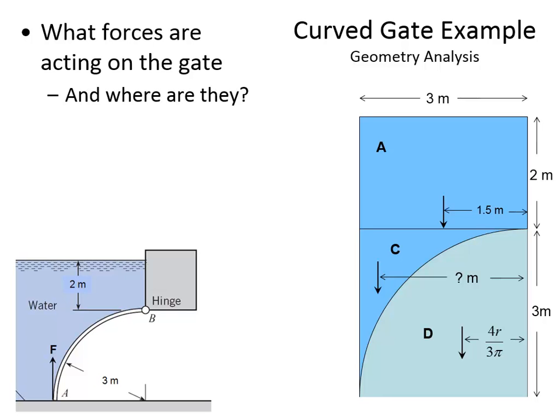Whereas delta H is just the vertical distance from surface to centroid. So in this case, our projection is vertically oriented, and therefore delta H and Y bar will be the same. Delta H equals Y bar equals 3.5 meters because the projection is vertically oriented.